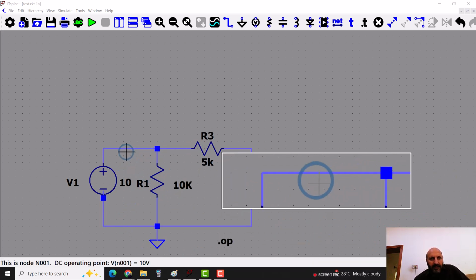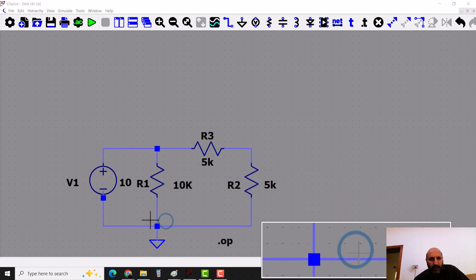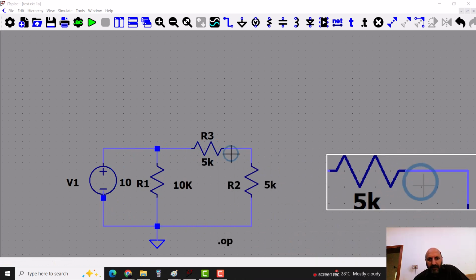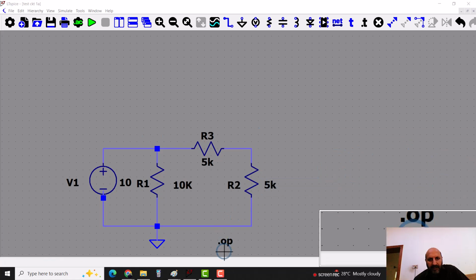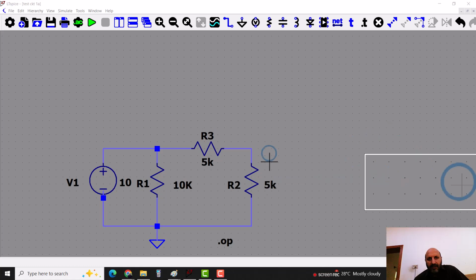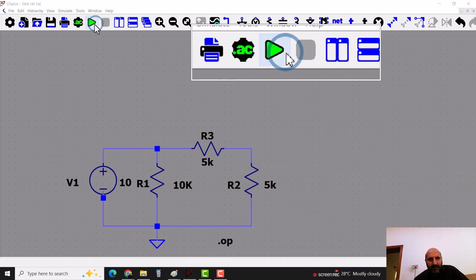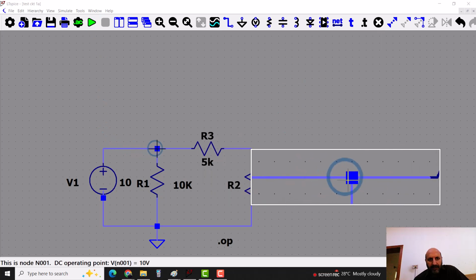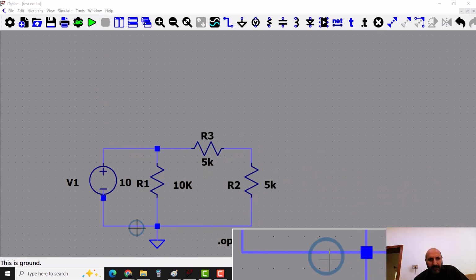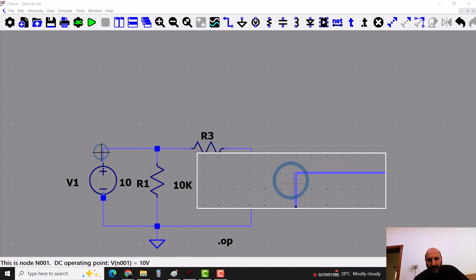So that is how, in the textbook, if you have a resistive circuit, you can do the nodal analysis directly from drawing the circuit in the schematic, and just click on the DC operating points and you can find the node voltages. Just placing your cursor after running the simulation from here, you can see all the node voltages and you can verify your results.